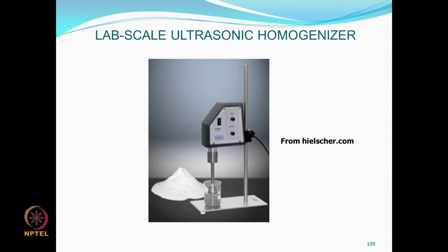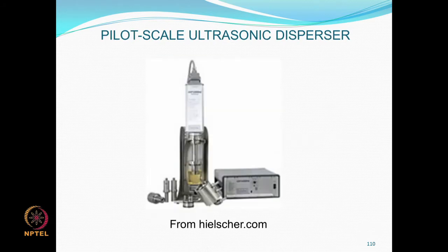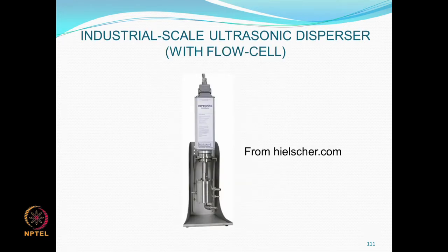Now there are commercial systems available for doing this. At lab scale, you can conceive of a simple beaker system with an ultrasonic probe that sticks in. So you put your particles in there and you turn on the ultrasonics, and fine particles will continue to be generated. You can scale this up to a pilot scale, basically larger size. The chamber volume that contains a particle suspension to be size reduced is now larger, so you can put more quantity of matter through this system. And finally, you have an industrial scale ultrasonic disperser.